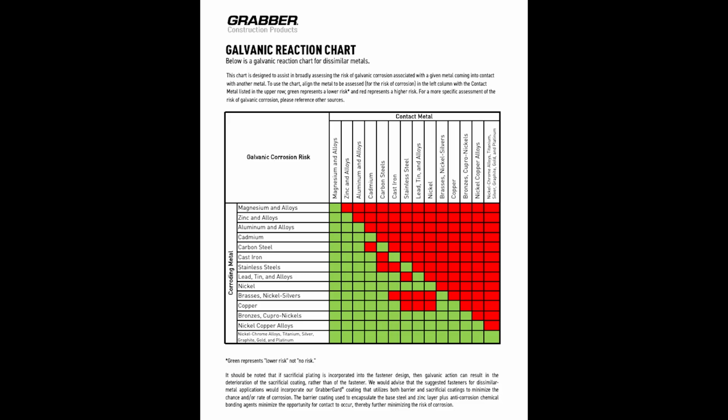And I'm talking here as if I'm an expert, but simply put, the further apart the two metals are on the galvanic series, the greater the electrochemical potential difference, and the faster the corrosion will occur. For example, pairing a piece of our stock 5052 aluminum directly with a copper bus bar in a humid environment is a recipe for disaster. So let's talk about some design strategies to prevent galvanic corrosion.